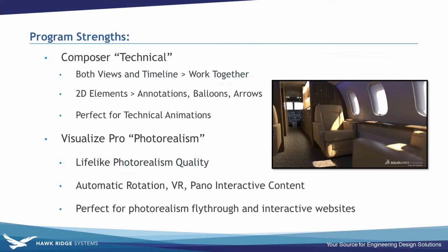Okay, so before we jump into the software, I want to talk about what we're going to show. First off, we talked about this basically already, but in Composer for the technical output, really the benefit is that you get both what are called views and timeline. When you're working in SOLIDWORKS Composer, you can do everything in independent views. Then you take those views, you bring them into an animation, and from there, you output your video. It's basically a free process when you're going from views to animation, and it's easy to create this real structured animation that way.